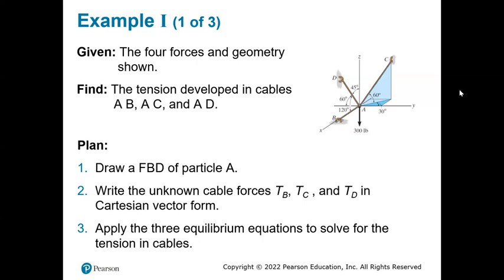You can ask why I'm representing them as TB and not FB. It's good practice to denote them as FB, FC, and FD, because in future, when we study trusses, which is very important, you will need that for mechanics of materials and other chapters. When you are studying that, it's better to mark them as forces because we don't know whether the force is going to be tension or compression.